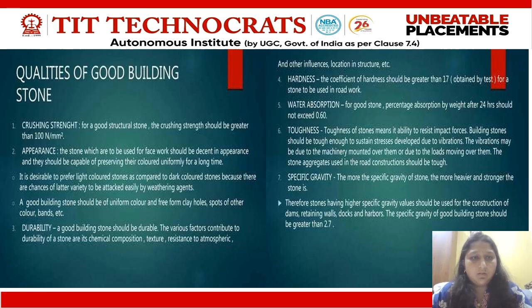Discussing the qualities of good building stone, the very first one is its crushing strength. For a good structural stone, the crushing strength should be greater than 100 Newton per mm square. As I've said earlier, it should be good in its appearance, it should have uniform color, it should not have any type of flaws.